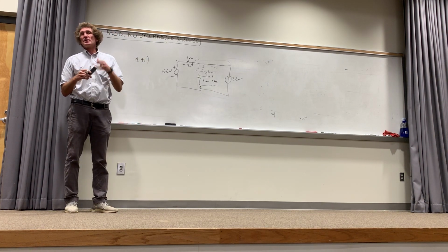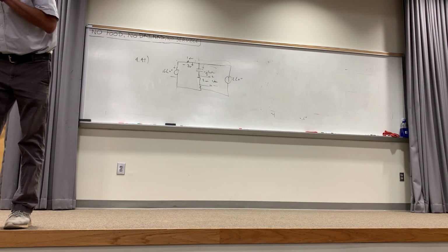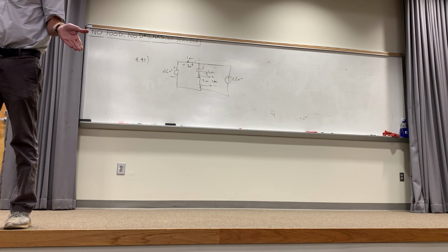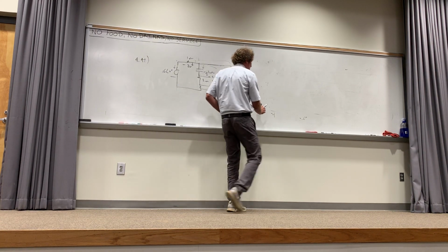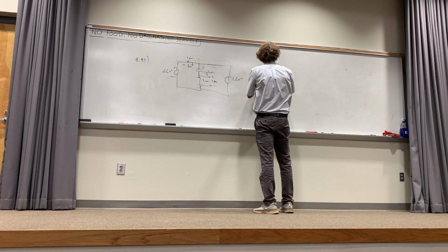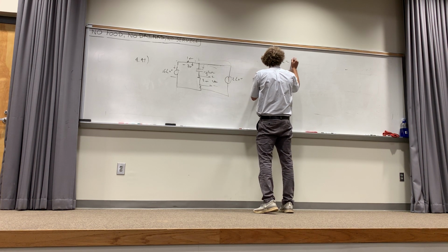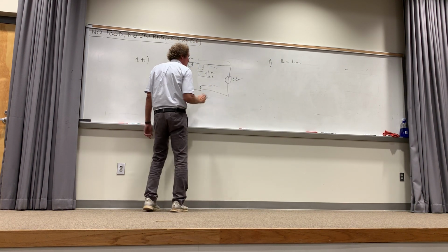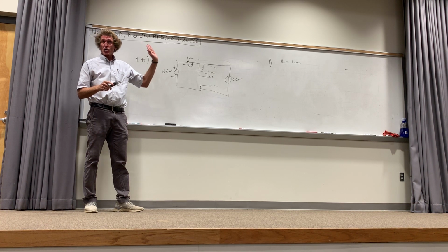And a question about Norton. Most of the time I ask Thevenin; sometimes it helps to do something with Norton, but you're going to see source transforms allow us to do it. Norton is a source transform of Thevenin's circuit, if you want the truth. All right, but I'm going to do the Norton. Norton's theorem says instead of the open circuit voltage, first you identify the load. So the first thing is still identifying the load, and our load is 1 ohm. Then you remove it, as before. But now, you don't look for the open circuit voltage, you look for the short circuit current through there.